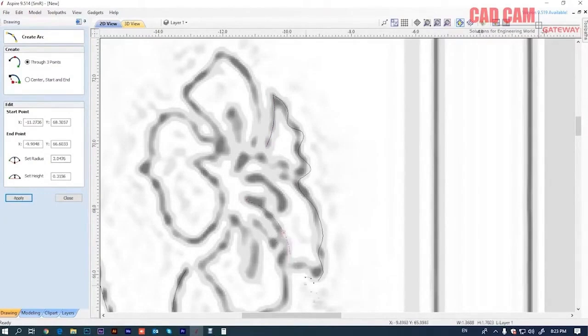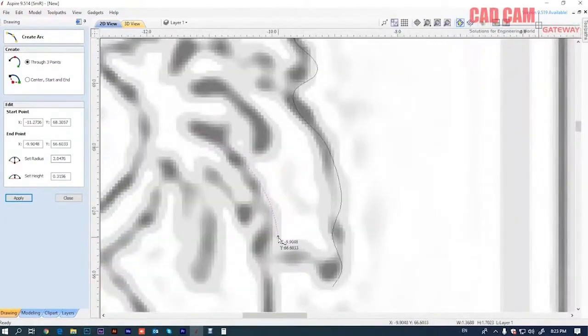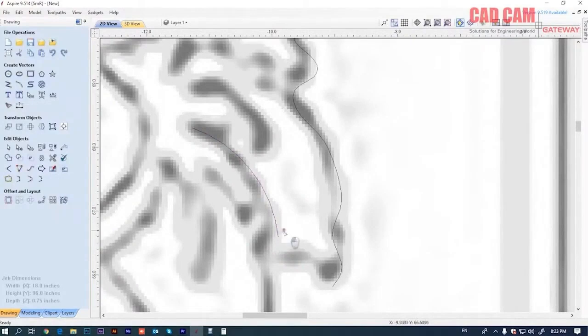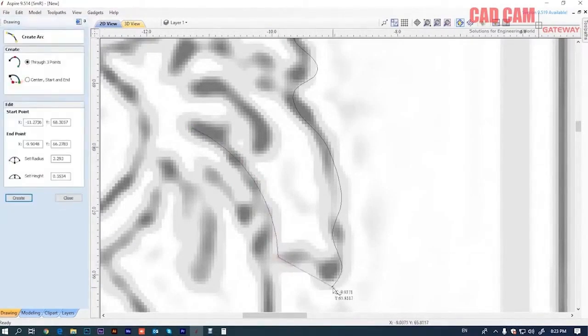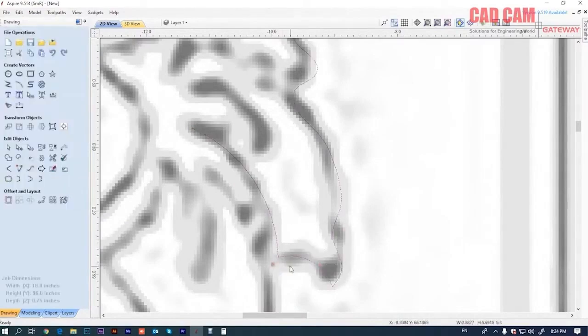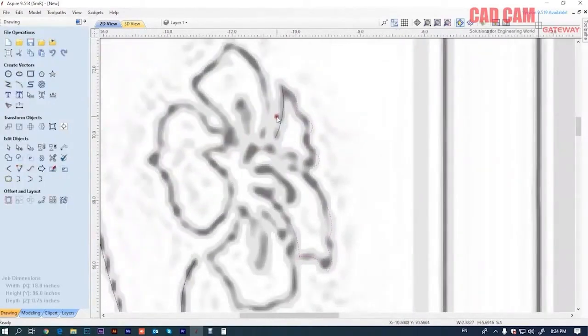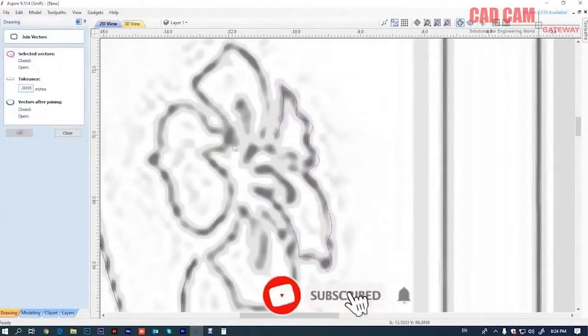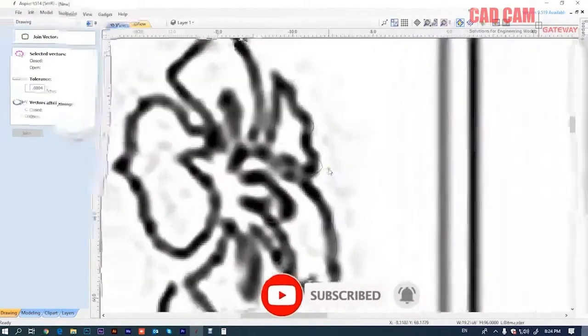Pressed it. The node option turned on, moved it slightly up to here. Then you select the arc command and connect these 2 points together and select all 4 objects and join them with the help of J, and this side's design is complete.